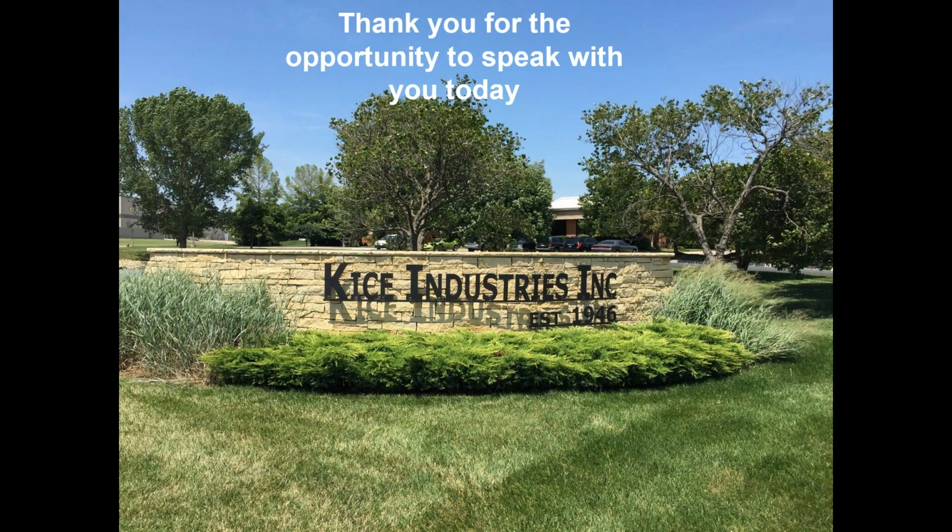Okay, next, how does cloth type, such as 12 ounce, 14 ounce, or 16 ounce, and air to cloth ratio work together? That's another good question. 12 ounce, 16 ounce, 14 ounce, that is going to speak more to filtration efficiency. It doesn't necessarily affect the air to cloth ratio.